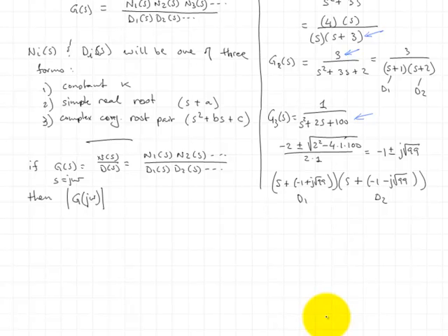we try to evaluate the magnitude, we can't, because to calculate the magnitude, we need to know what the contribution is of the real term and what the contribution is of the imaginary term, and those are in quadrature, right? So to determine the magnitude, you take the square root of the sum of the squares. So we have to assign s to whatever its ultimate form is. We can't just say it's complex. We have to know how much real and how much imaginary there is in it.